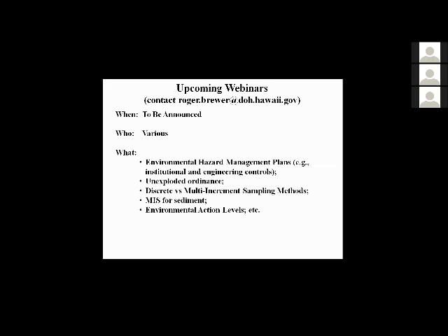Gases will not be moving then, but as the water subsides after the rain event ends, gases will then start moving again. And because we're using hydrophobic adsorbents, they will continue to absorb compounds even if they become wet. It's not necessary to have a membrane or plastic around them to protect them.